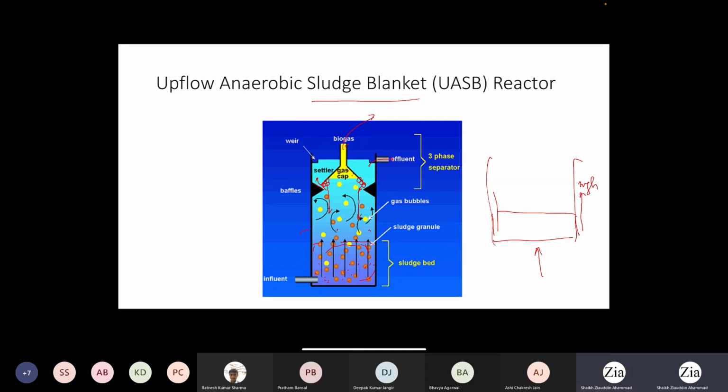If you remember, in between the cone and the notch of this reactor system, only liquid will go out and all solid will get arrested on the cone, and they will again come back to the liquid system due to gravity. Gas will get collected at the top, and through the gas vent it can either be collected in a big balloon, or we can have a gas supply line to use that gas elsewhere.